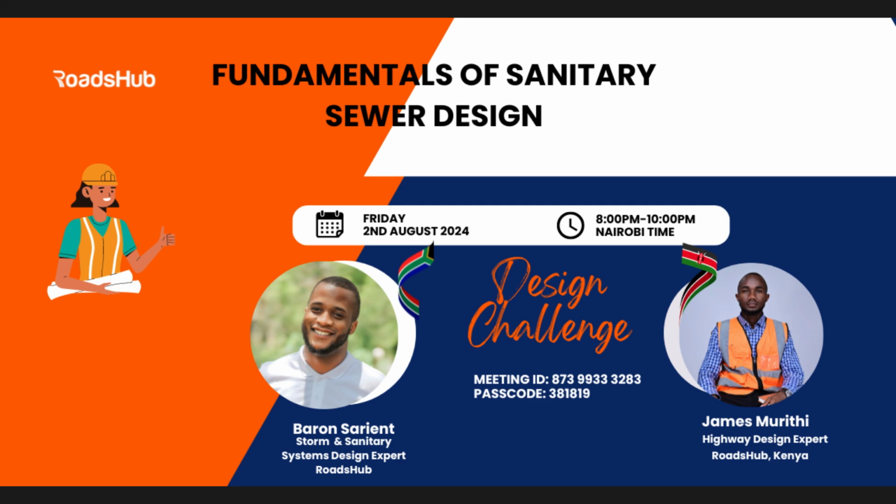When the slope is not at the recommended height, or the slope is not good, we shall find challenges like clogging of the sewage or any materials in the pipe, which will reduce the pressure or the size of the water or any sewage that is coming through the pipes. Therefore, in the long run, we shall have challenges with our design of the whole system.